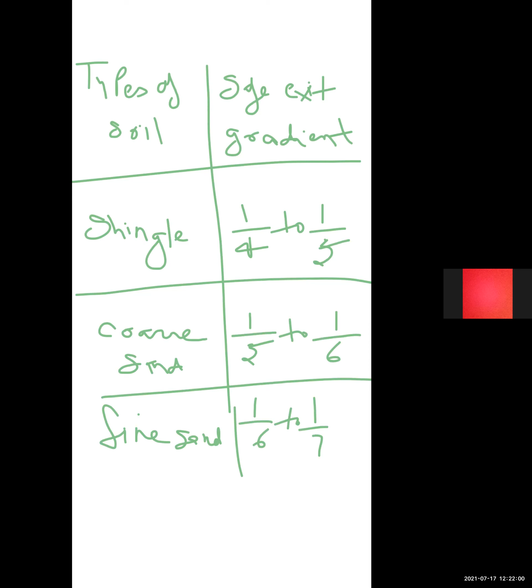So Khosla's theory of flow net makes it very clear that the loss of head does not take place uniformly in direct proportion to creep length, as stated by Bligh. It depends on the whole geometry of the figure, that is the shape of the foundation, depth of impervious boundary, and level of upstream and downstream water. So when the equipotential lines are traced closer, the rate of loss of head will be indefinitely quicker, and vice versa.